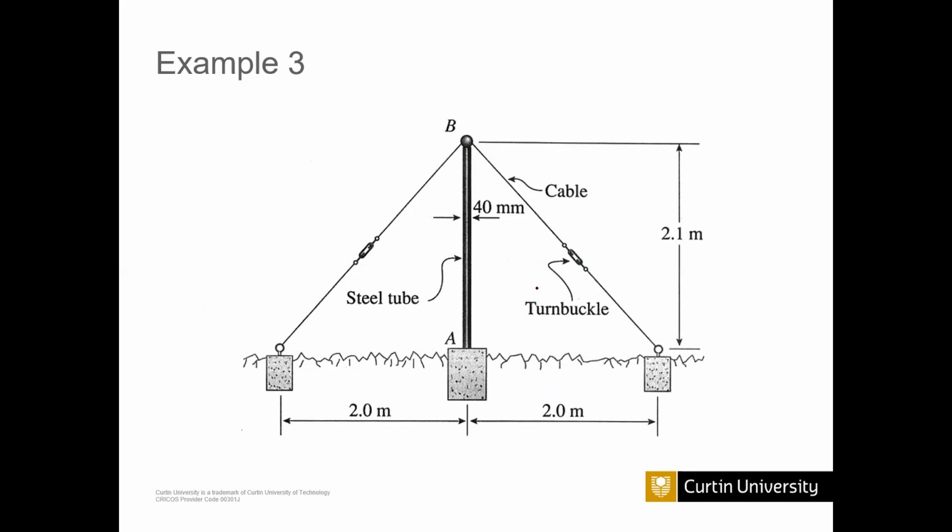There is also this kind of turnbuckle, so they will tighten and increase the tension of this cable with this turnbuckle. There is a screw, I mean threads, you can tighten that thread, then tension will be increased and this post will be balanced like that.